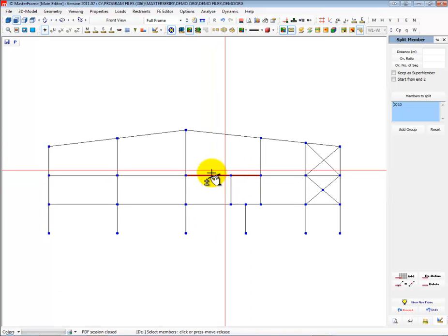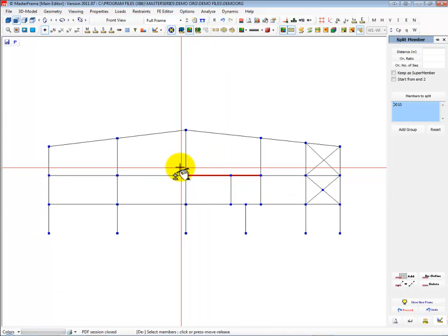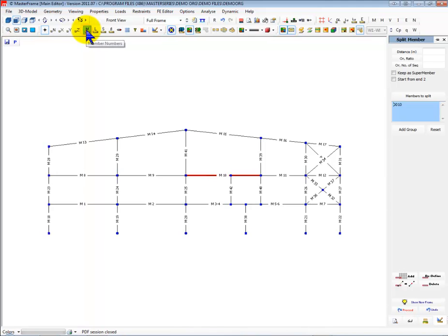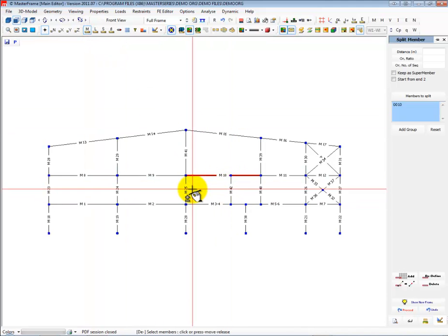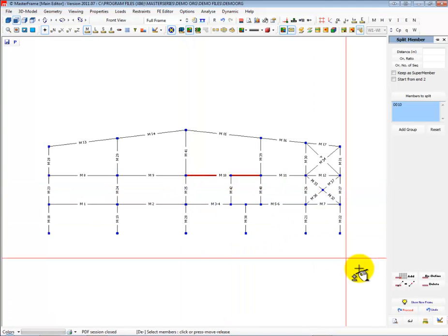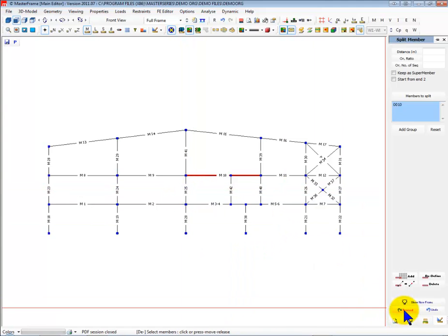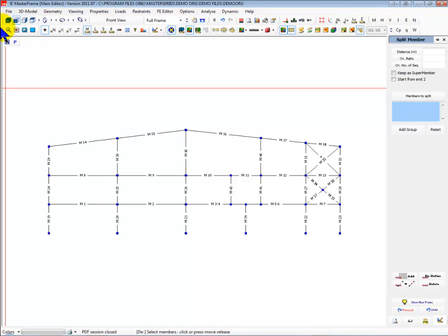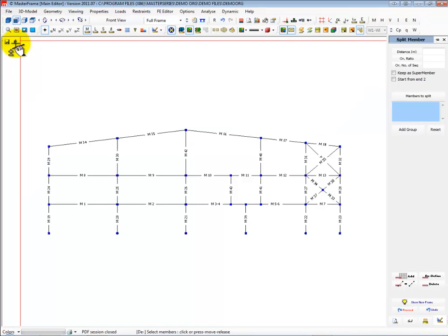It's got an instability here because I think that was just one member. Yes, it is. So this column was sitting up here, probably pinned and just flopping about, and I will just go auto split, proceed. So Tommy, you should always listen to what it says on the error reports.